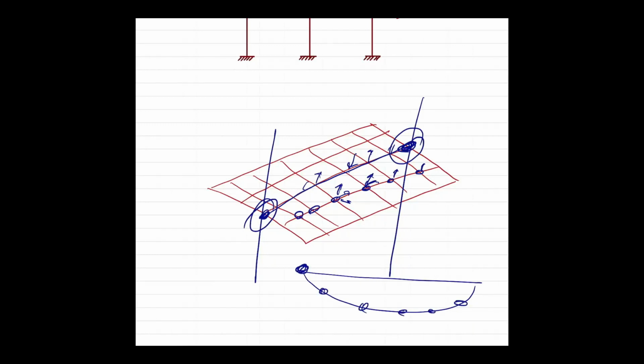And using the beam like this, the beam is discretized by having just nodes 1 and 2. So you don't have a degree of freedom in between. Whereas for your plate, you have DOFs everywhere in between. But you don't have any on the beam, so how do you link these two? Turns out to be the issue. And once the analysis runs, you complete it.